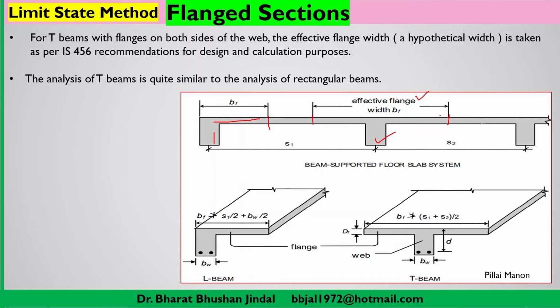So what width of the slab above the web or above the beam can we consider as effective flange? Here you can see that S1 is the center to center span length between these two beams, and S2 is the center to center span length of these two beams. S1 and S2 may have the same value. Now let us talk about this T section.